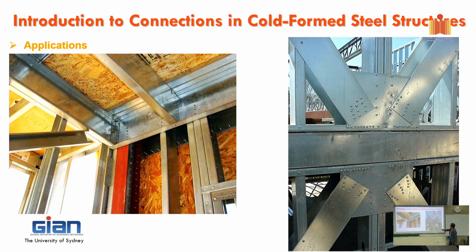All right, so you can see in here there's a screw connection, and they can screw together a bunch of these. It's a built-up section, not just one section; there are three sections put together to make sure you have enough capacity. And not just for small components or small structures. You can see it's a bracing of a big structure, so they have a bunch of screws in here as well, just to make sure they have enough capacity to carry all that big load.